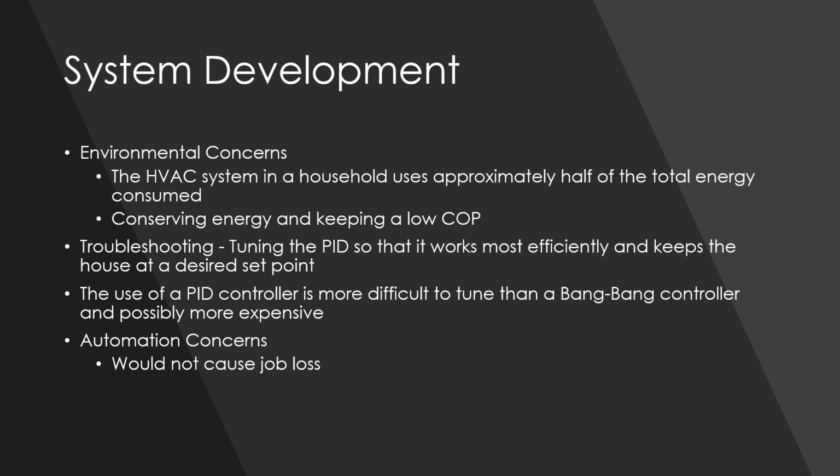Troubleshooting for the system mostly is tuning that PID as well as we can so that we get efficient operation and we keep that desired set temperature point. The problem we run into here is that the PID controller is more difficult to tune than that traditional bang-bang controller that's mostly seen in houses, and it can possibly be more expensive. I'm not really concerned with automation, as this really wouldn't cause job loss.